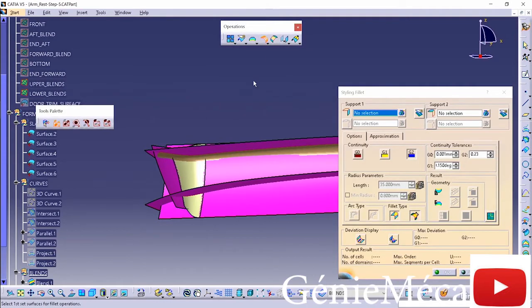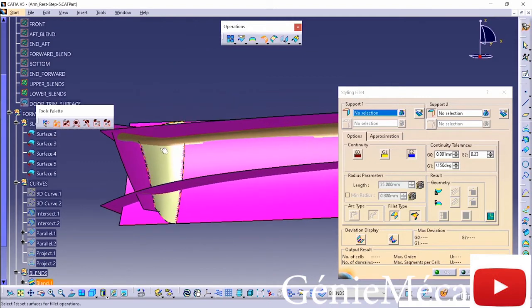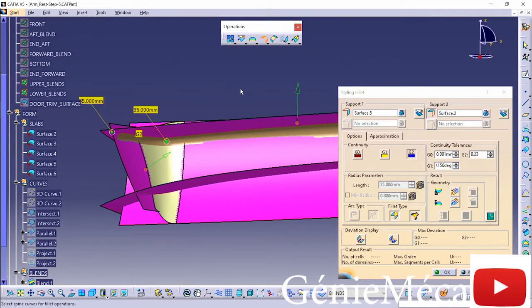I'll go ahead and double click on it and pick my end cap to that top surface. Let me reverse the direction. And I want to make sure that variable is turned off. I want to make sure G2 is selected. I want to make sure that the arrows are pointing in. And I want to have a chordal fillet going through that. And I can begin typing in some numbers here and see if that matches up.